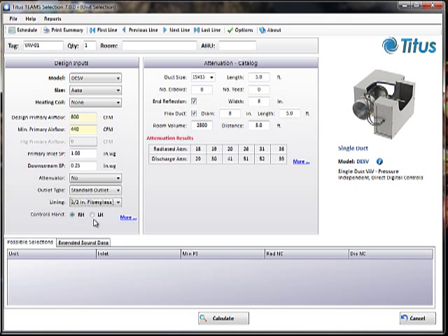Now you can pick right hand and left hand of the box. This is more for when our reps go to order it, but it allows you to select it here, and then that information is exported into our pricing program later. This middle section is for catalog attenuation. It tells you the attenuation used to get the room sound pressures, and therefore the NC, for this box. You can get pretty specific.